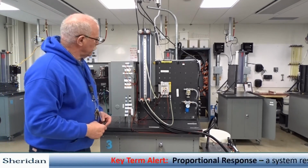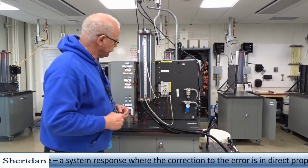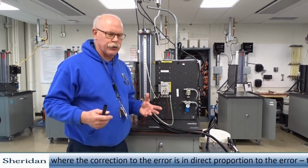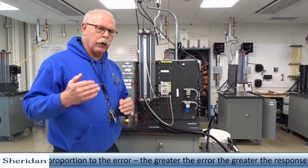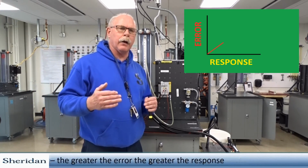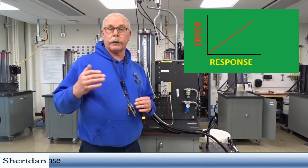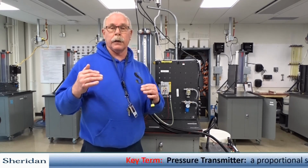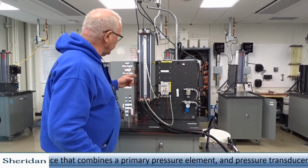Okay, so in this lab what we have is a proportional control, which means that the corrective action isn't constant, it isn't the same all the time. It also takes into account what the error is. So as the error becomes greater, the corrective action becomes greater, so we bring it back in line with the set point. So we have this proportional control.